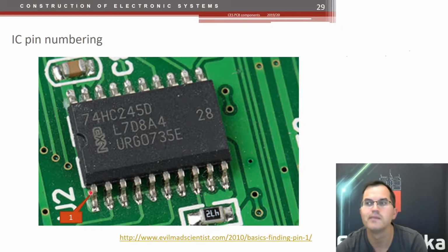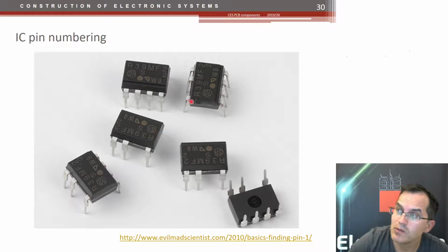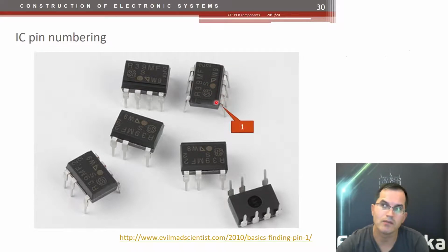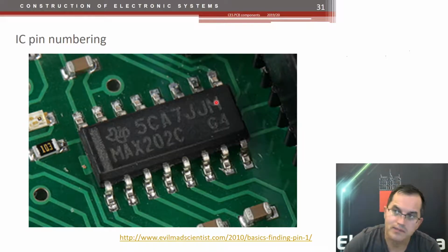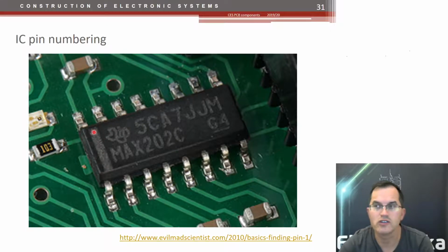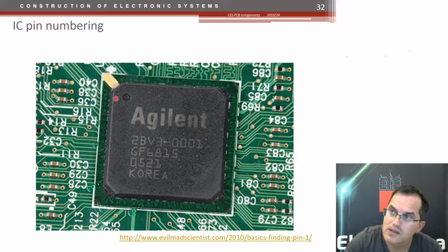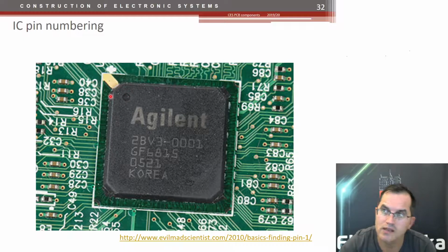Okay, this is pin 1. Here, pin 1 is here. It's marked. This is the bottom side. It's grinded here. So pin number 1 is here. Here, the side is grinded, and here you see the line which denotes the left hand side. Again, this is pin number 1. Here, this is the marking, so pin number 1 is here, and then we go counting in clockwise direction.